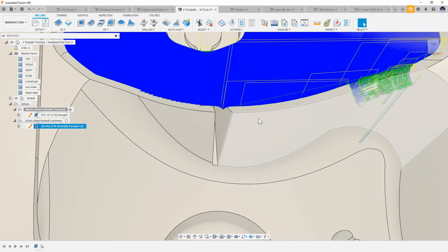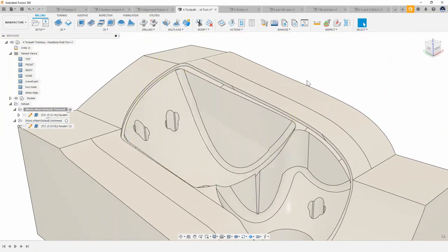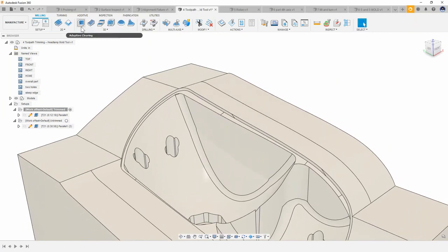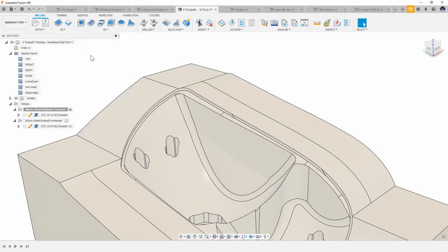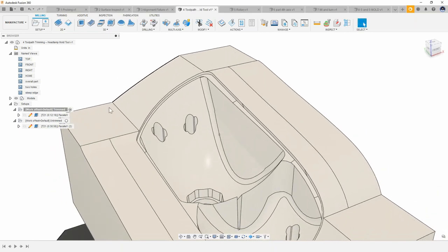So toolpath editing and trimming can be done on finishing strategies. This is limited today to finishing strategies only. Roughing strategies, if we did allow the customer to do that, it would not be intended for a user to eliminate the top part of their roughing strategy and have their tool crash into the stock. So we are trying to keep it safe there, and that's why the other strategies aren't allowed.